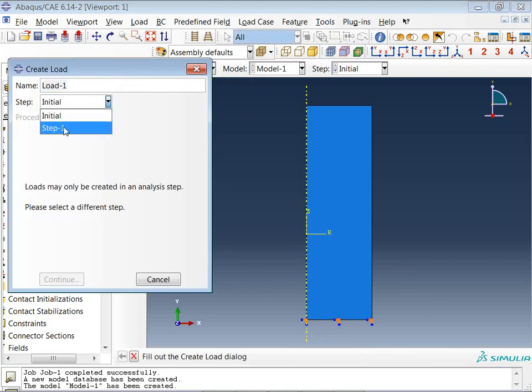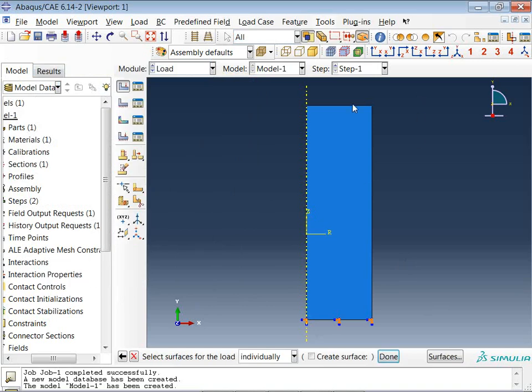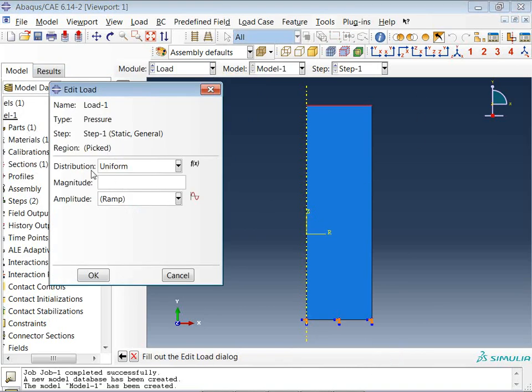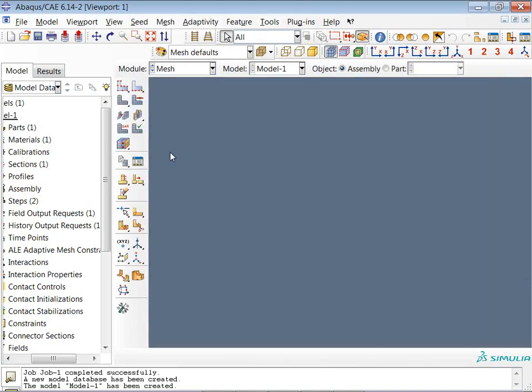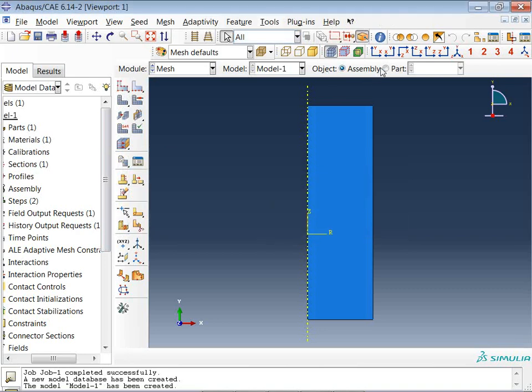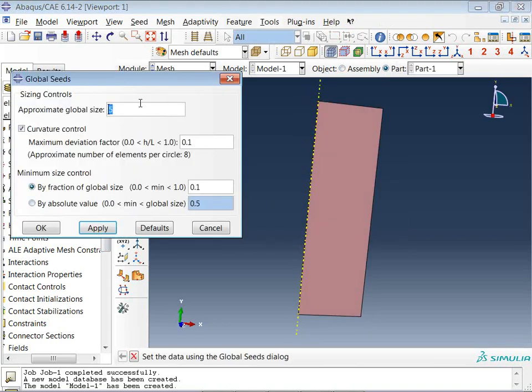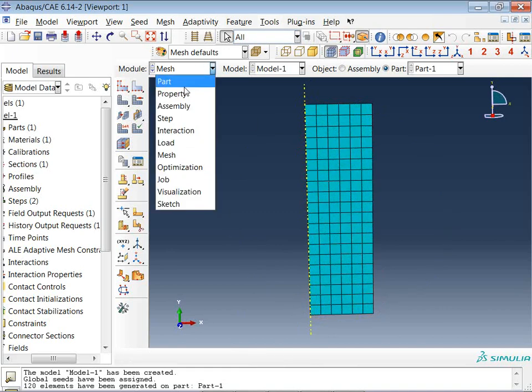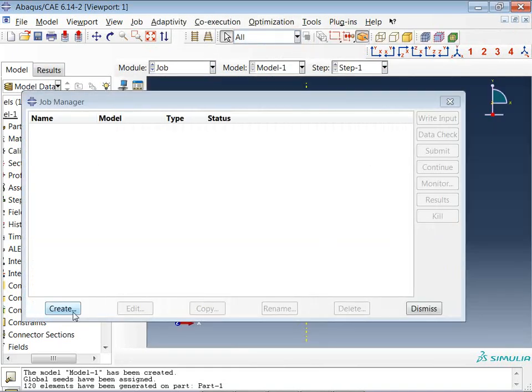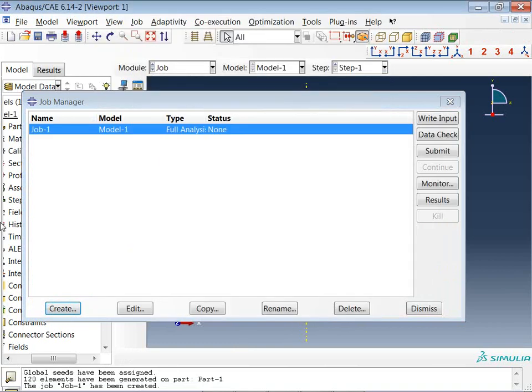So your mesh is also generated. Now solve the problem. Now it is solved. Check for the results. As you can see, the same result, same pressure, same everything. Now you want to see your model completely. It is now a 2D surface only. How do you ensure that your model is 360?